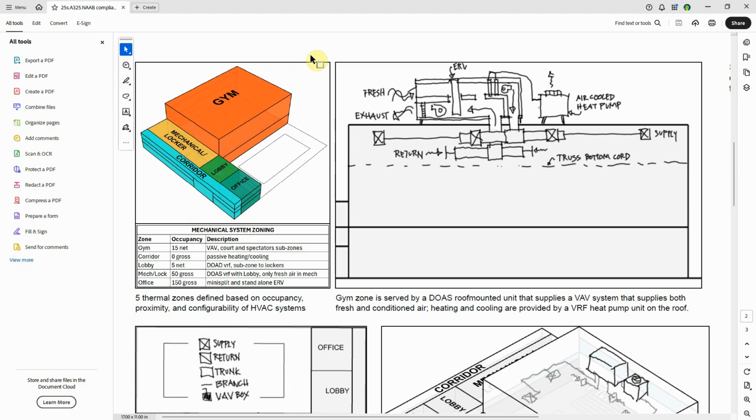As a reminder, a thermal zone is simply a box of air that's separated from outdoor air, the ground, and other zones, and it's defined by the number of people in it, the amount of activity, the amount of equipment, whether it's facing toward the sun, the amount of wind blowing against it, etc. All those variables will determine a certain amount of heating, cooling, and fresh air that zone needs, and that will define it as separate from another zone next to it in the building.